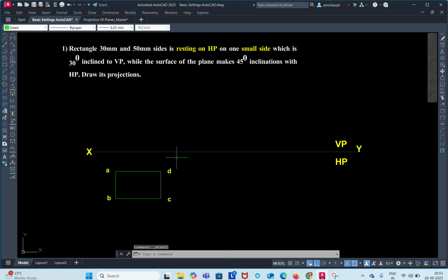Now I want to draw vertical projection lines from every point of this ABCD to get the corresponding front view. From this top view of the object, you have to draw vertical projection lines up to the reference line to get the front view, or true length, of this object. So draw the vertical projection lines up to the reference line.